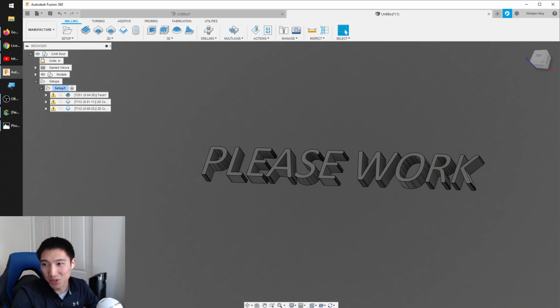Different tool depending on which machine you had. It really depends on the size of the piece you're making. So for something like my little quarantine sign, for reference, this is the size compared to my face. It's not big. The features you're cutting out are going to need a tiny end mill to get into. So a 16th inch end mill works on both the Nomad and the Shapeoko. If you're cutting out even smaller letters, you might really want the Nomad, especially if you're cutting letters out of brass. I did a brass inlay for my friend, and those letters were like 3/8 of an inch tall, and that really needed the Nomad's high precision spindle.